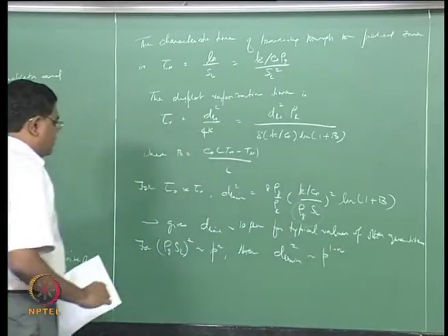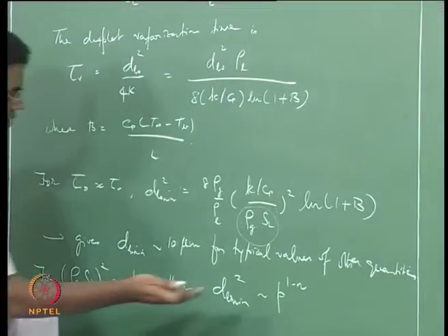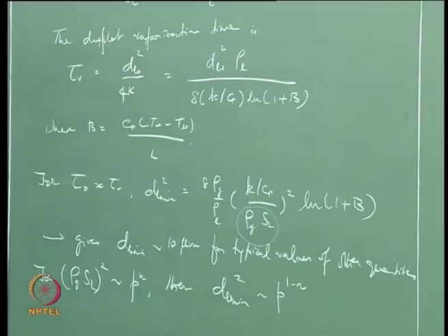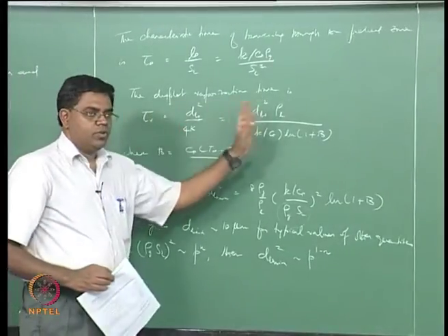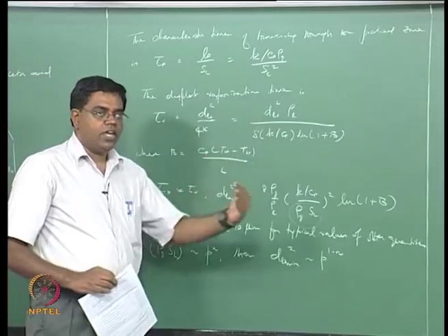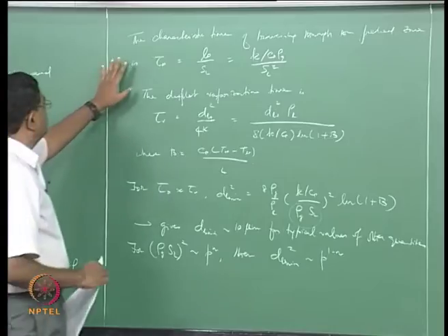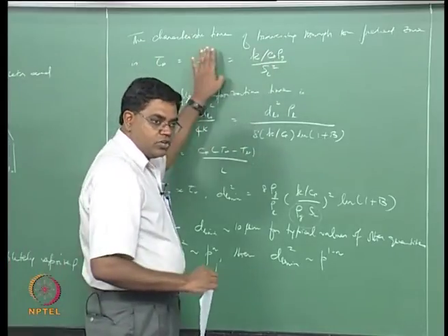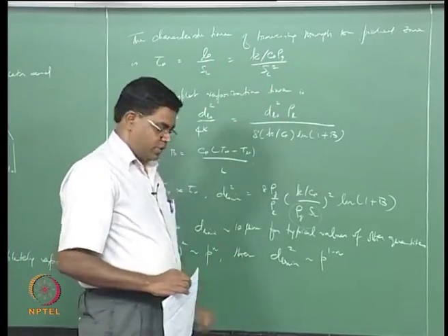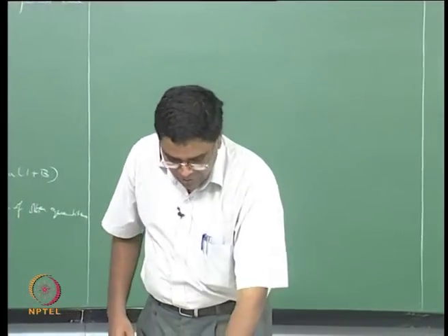What this means is the pressure dependence purely comes from the preheat zone length, and we don't have to worry about the dependence of the evaporation time on the pressure. The evaporation time is not dependent on pressure, it's only the preheat zone length that changes with pressure, and therefore the residence time of the droplet within the preheat zone is going to change like this. So that's mainly the effect of pressure.